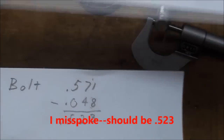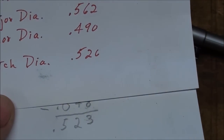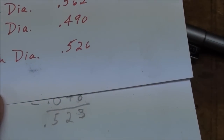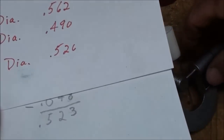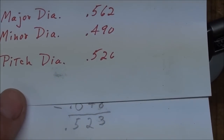Now the actual pitch diameter should be 526. That's only 3 thousandths off, so that's mighty close. You know, just 1.5 human hairs off. And they have to allow for plating also in the plant, the thickness of the plating. So that's really a good job of what they did there on that commercially made bolt.